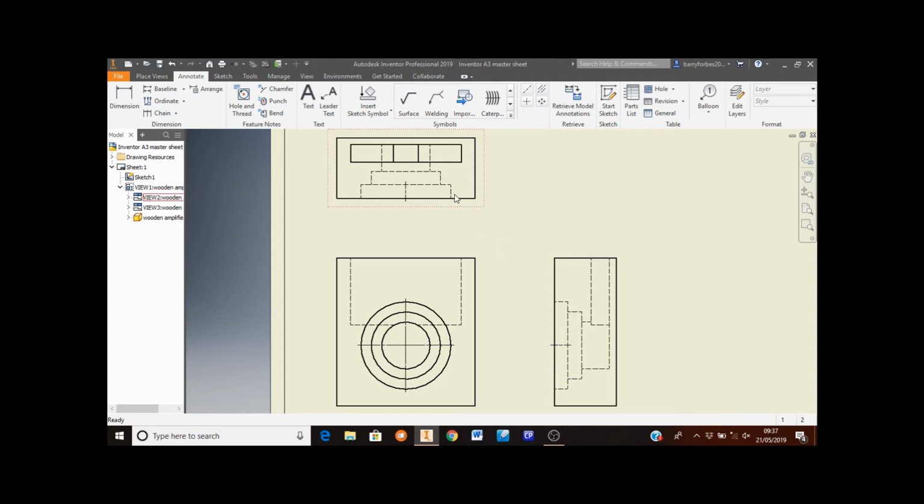For these 2 smaller center lines you just put in, you can also see that there's a circle shape here and also here. So I'm going to move the mouse to this green dot here and drag that center line to go through all of these. I'm going to do exactly the same in the end elevation. And that center line now goes through all of the circular shapes I need on the elevation, the plan, and the end elevation. The next thing we're going to do is label these drawings.